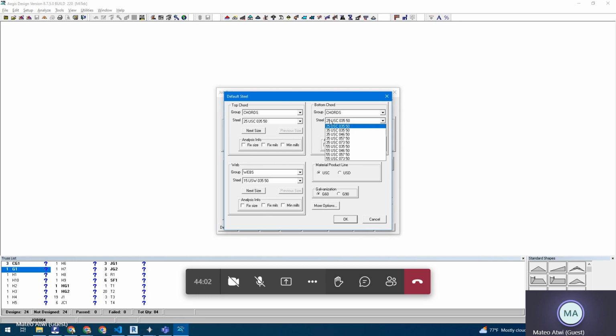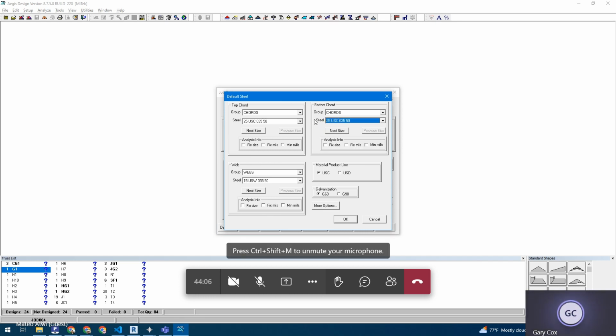It's starting at the minimum, and then it'll get larger as necessary. But on a truss by truss basis, you can go in and say, I want to fix the size of this, my bottom chord. Don't make it larger. Because sometimes it starts to cause problems if it needs to be too thick, because your heel height is kind of shallow. One of those things.